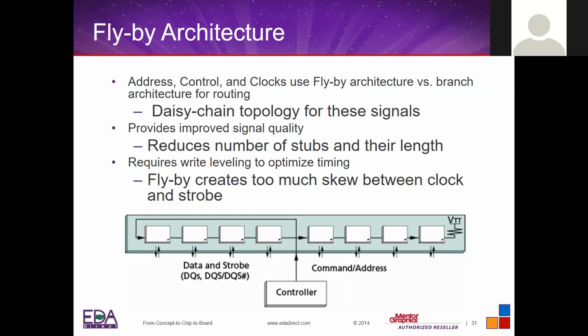Let's say you're doing this as a T routing. One address line takes one path to 4 chips and takes another path to the other 4, right? Hey, I'm keeping the length to be the same. Well, that creates signal quality type issue, and you can look and detect those in simulation to see if it's okay or not.